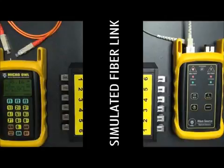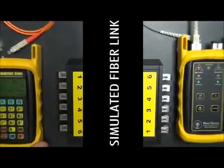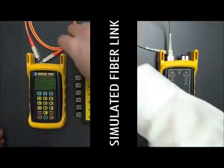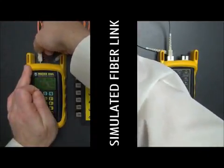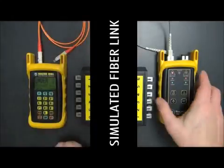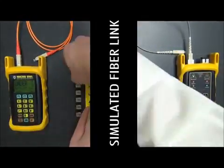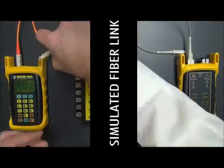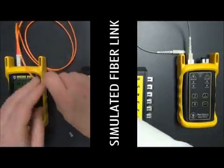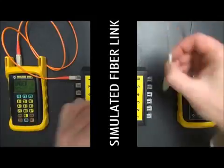So now that we have our equipment on opposite ends of the link, here, let me zoom out a little bit more so I can see better. We can take our patch cables and plug them in to port number 1. Obviously we want to start out at the beginning. Port number 1 is the best place to start. So we take our patch cables here and we connect in to fiber number 1.